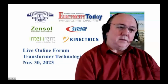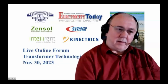Yeah, when they redesign breakers, have they redesigned them in a way to make them more reliable? Yeah, I think the newer stuff is definitely more reliable. Like I said, I think we went from, oh gosh, I don't know, 30-something lube points on the old ones. I think on a lot of the newer breakers, you're looking at 7, and some of them are none. They have greatly compacted and simplified the moving parts that are involved.